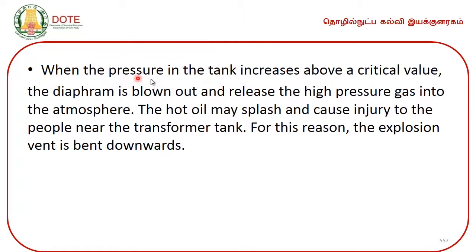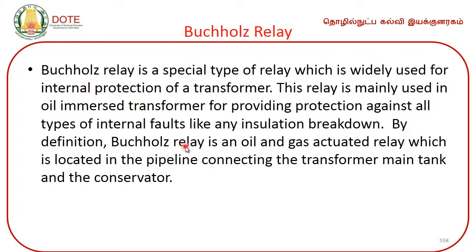When the pressure in the tank increases above a critical value, the diaphragm is blown out and releases the high pressure gas into the atmosphere. The hot oil may splash and cause injury to the people nearby. So, for this reason the explosion vent is bent downwards.